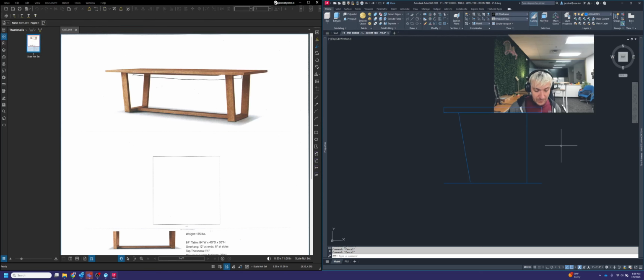So we're going to use that rotate command one more time. And instead of 10, you can either type in 350 degrees, which would be 10 degrees less than a full 360 rotation, or you can type in -10, like that. If you type in -10, it's going to rotate it 10 degrees in the counterclockwise direction. Because you always have to remember when you're dealing with angles in AutoCAD, AutoCAD really, really likes going clockwise. So if you want to go counterclockwise, you either use a negative number or you have to do the math and figure out what that would be.